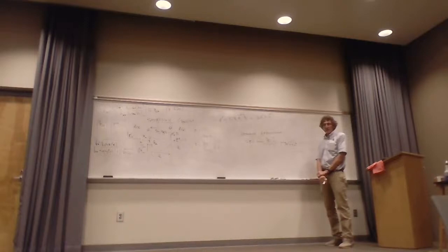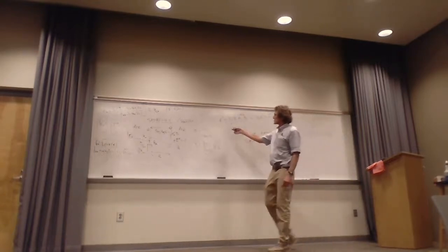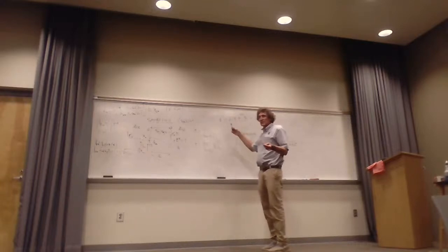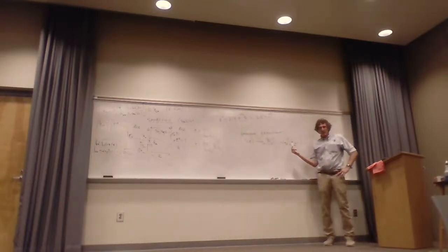Make sense to everybody? Shielding effectiveness is used because usually the electric field that's transmitted is 10 to the minus 4th, 10 to the minus 5th, 10 to the minus 6th of the value of the incident field. You get so many orders of magnitude that it makes sense to talk about the logarithmic change, or 20 times the log of that value. Think about this.